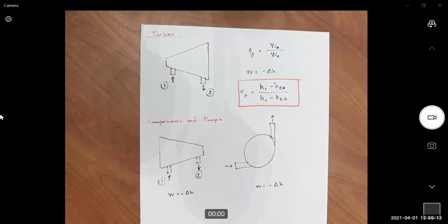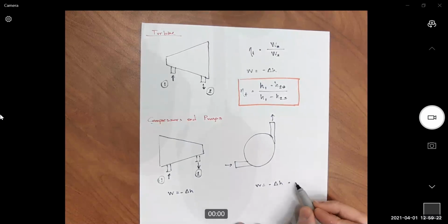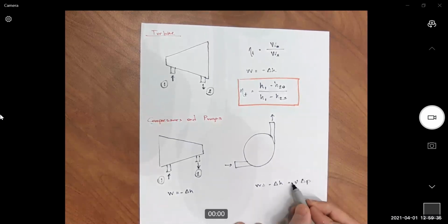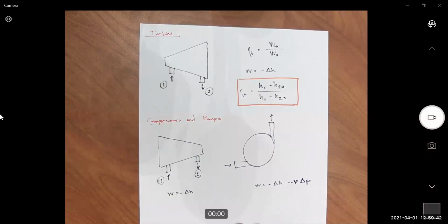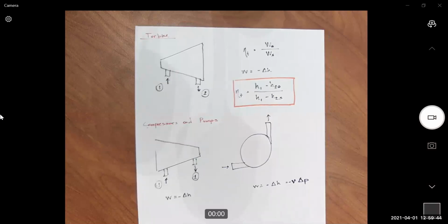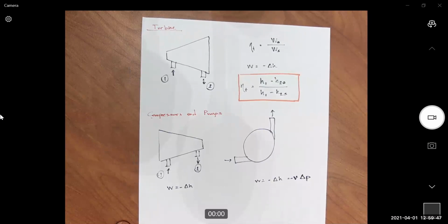So if density is constant, meaning specific volume is constant, right? So both are inverse of each other. So I can tell, by using specific volume constant, right? Delta H equals specific volume times delta P. There's a minus, minus. Remember, this is only for incompressible liquids. Okay?